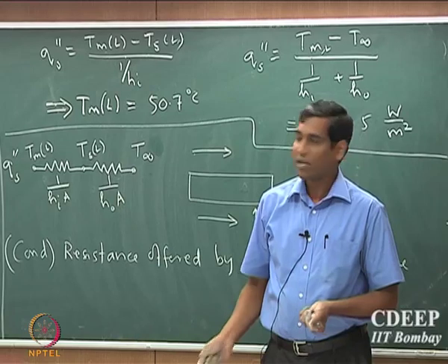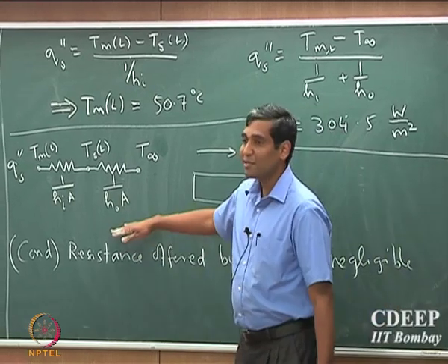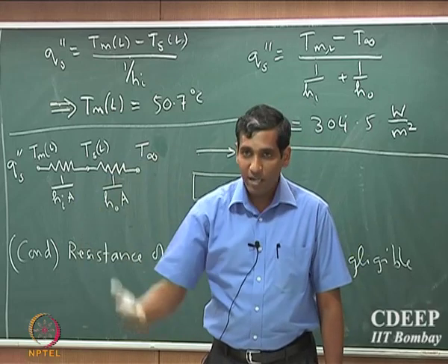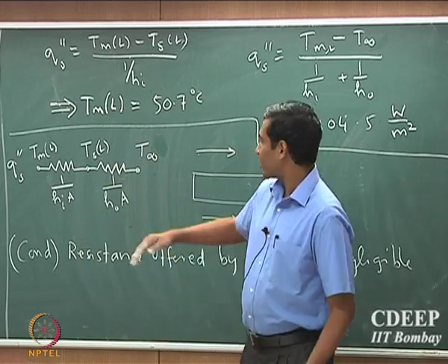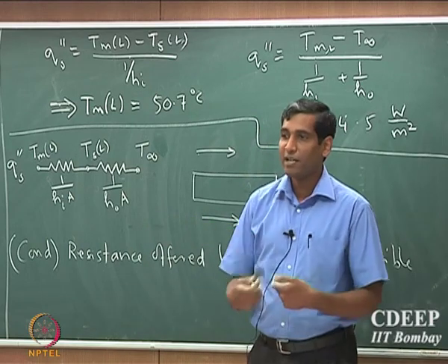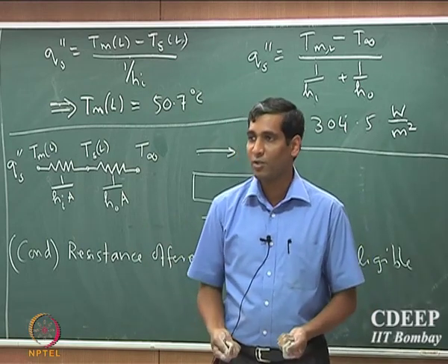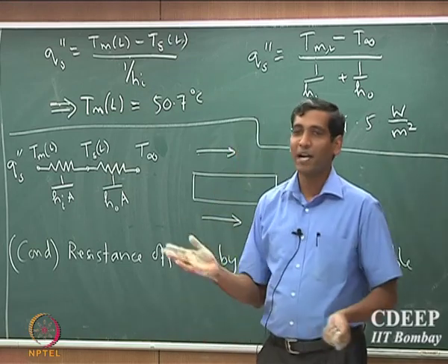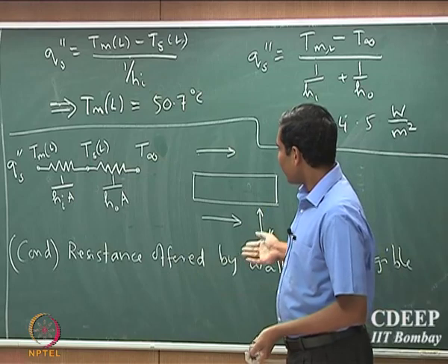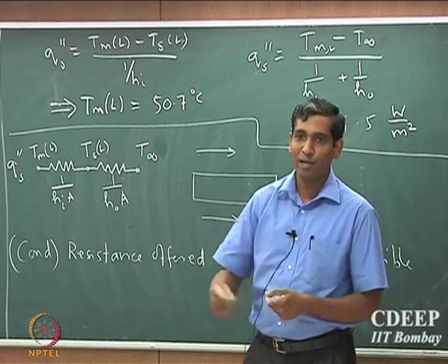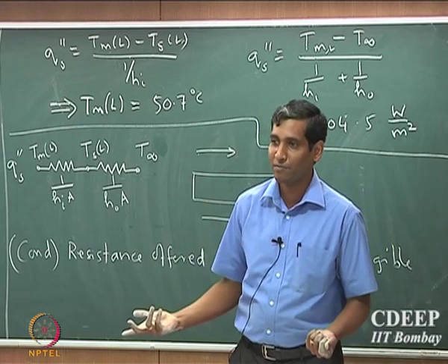Okay. So, remember that the resistance concept that we actually developed and discussed in conduction topic actually comes very handy. So, when you have simultaneous conduction convection processes, if you do not have any heat generation in the wall, which is not a bad assumption to make, you can see that these resistance concepts you will start seeing that it is coming in again and again in many different scenarios.